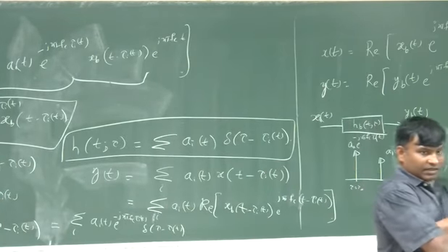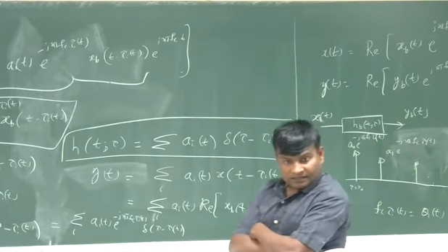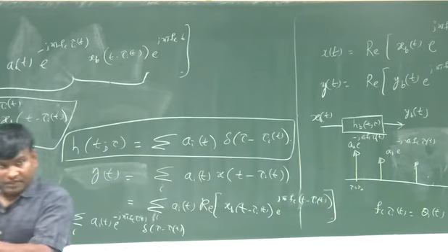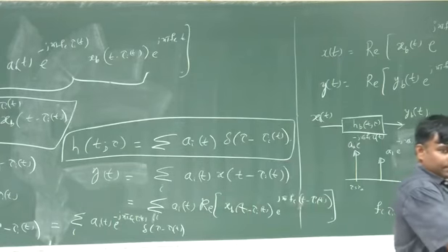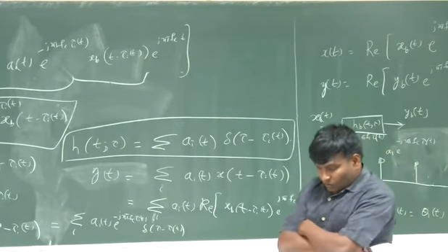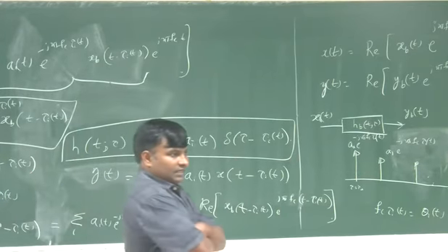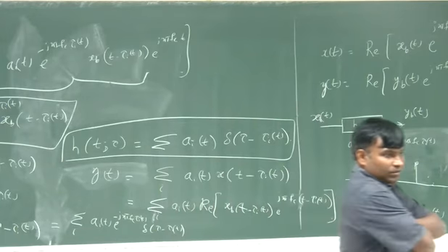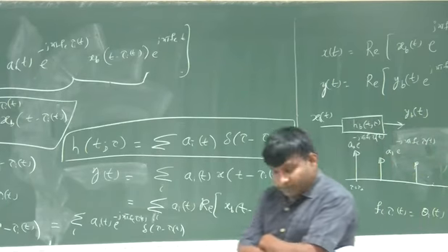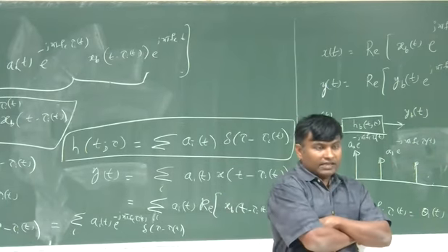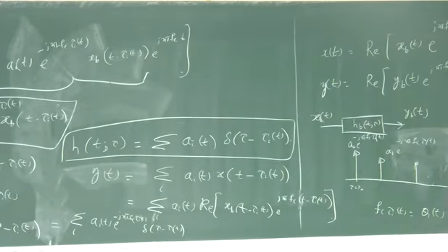at some point in the receiver, you might apply, let's say, a matched filter or some other operation, like an equalizer. But in many systems, we bring the signal to low pass baseband form and then apply a low pass filter that limits the signal to the effective bandwidth W, where W is equal to 1 over T. Then we collect the samples at the output of the receiver.